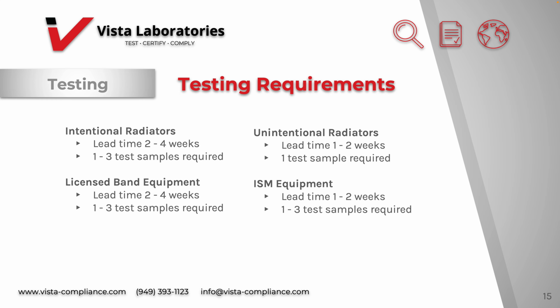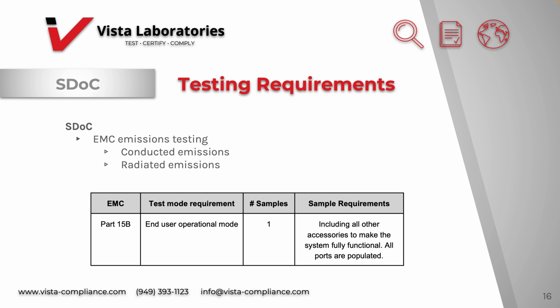Generally, separate samples are needed for the RF conducted part and the radiated measurements. Samples must also be able to sweep over the full spectrum continuously. If there are multiple radio functions, multiple samples will be required if each sample only supports a single radio function. The measurement process will naturally take longer if there is a need for troubleshooting.